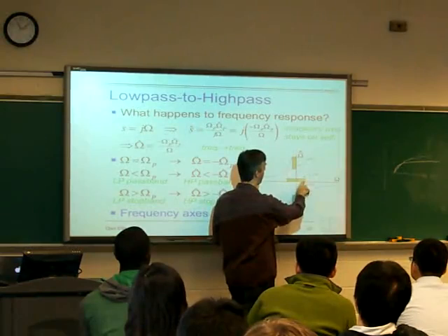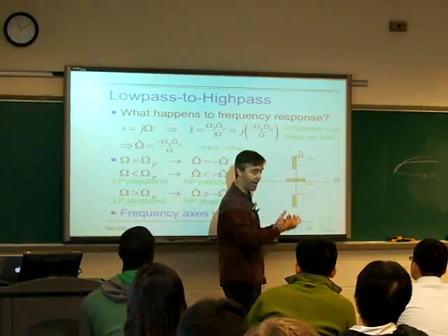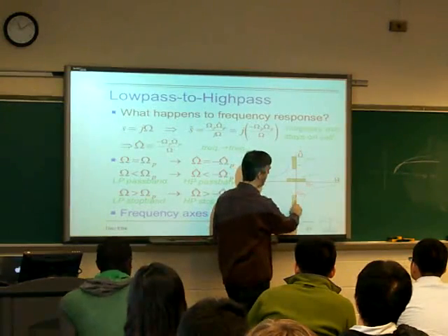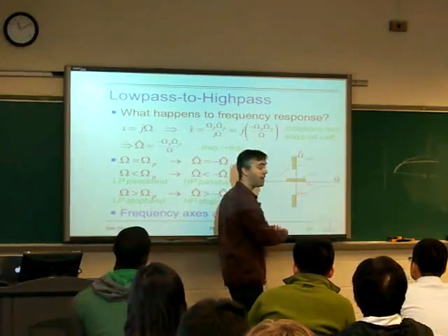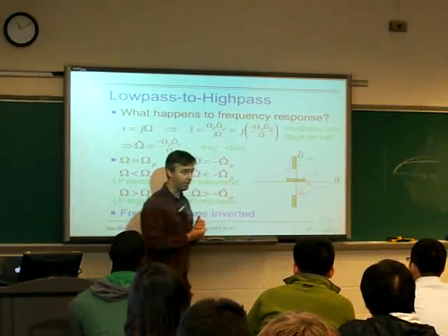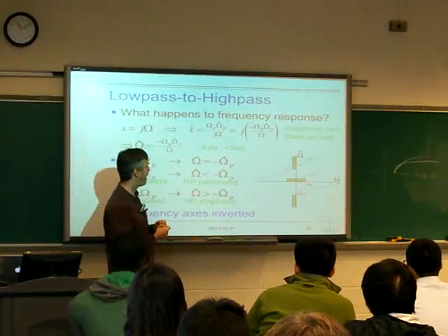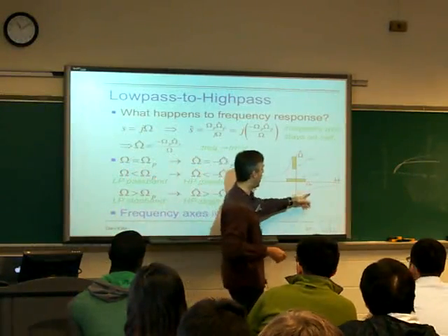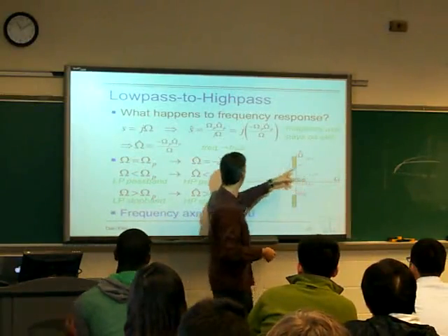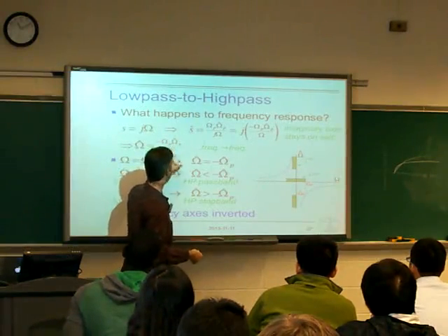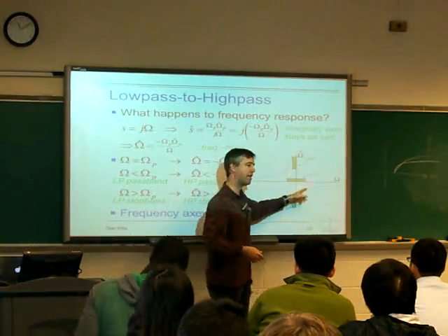And all these points up here that were the pass band, with gains within epsilon squared of 1, are now frequencies out here above omega p. So we get a high-pass filter. So what's the blue line? The blue line here is just the actual mapping from this. The blue line is just this, minus omega hat p divided by omega, minus 1 over x, right?